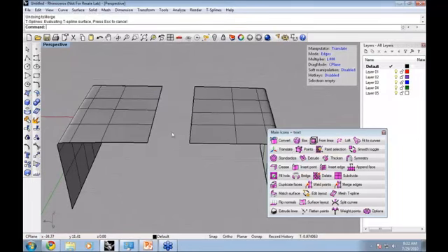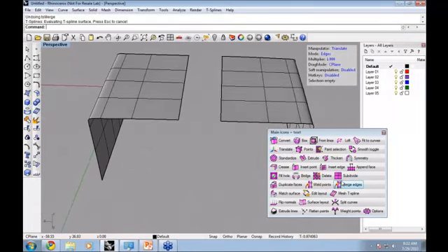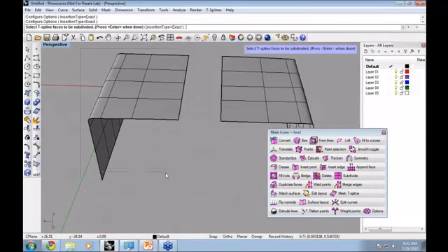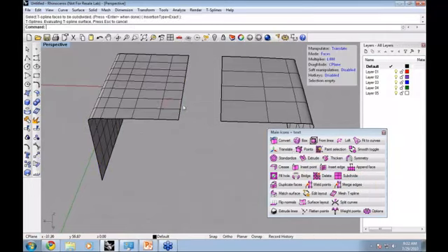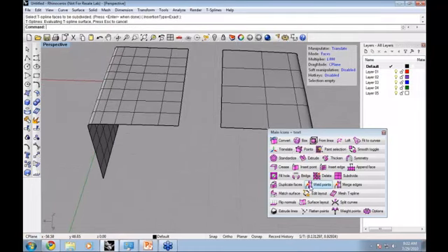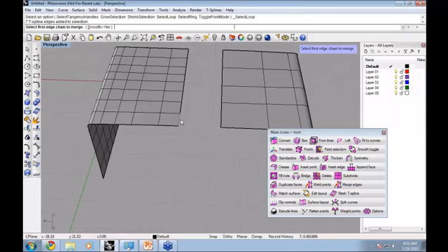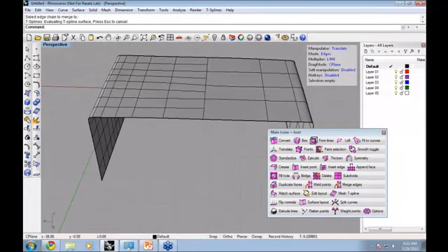So we could show that by, I'm just going to run the subdivide face command to just subdivide all these faces. So we have like twice as many here now. And the merge command will still work if I'm just going to double click to select this whole edge, and then double click to select that whole edge. You can see it still merges nicely there.